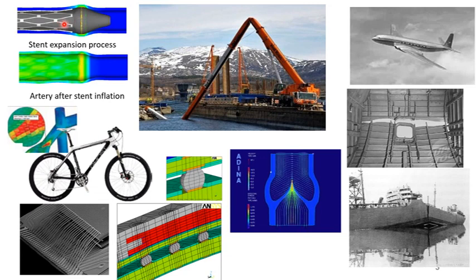They put in a stent, and the stent causes some permanent deformation, so you cannot do experimentation all the time. In order to design the stent or its expansion, you can use a numerical method and reduce the experimentation. And this is the deformation and stresses on the wall.